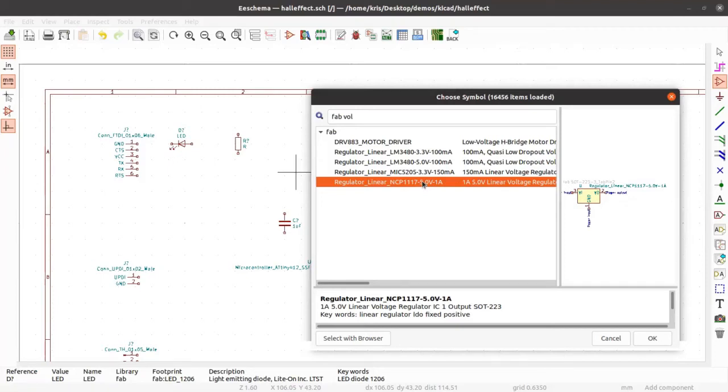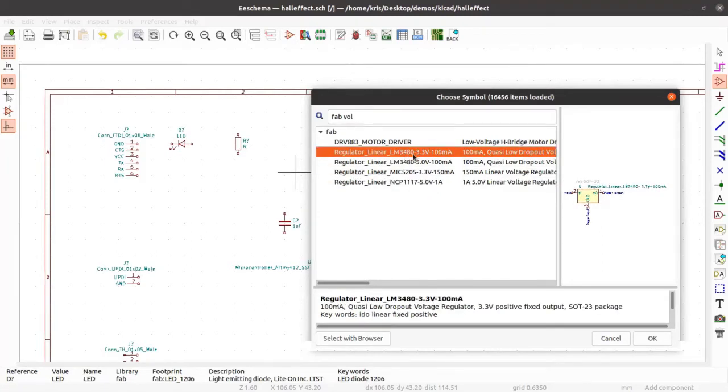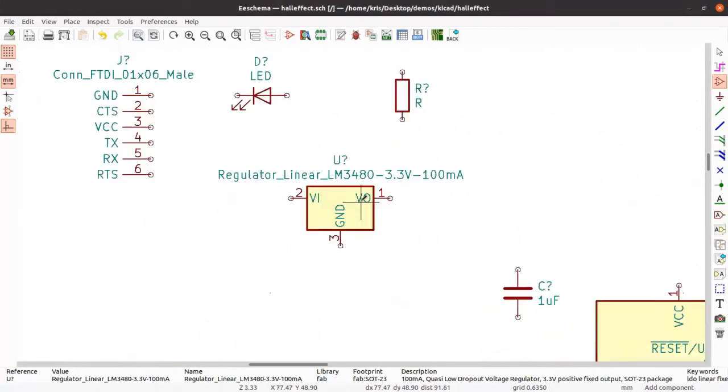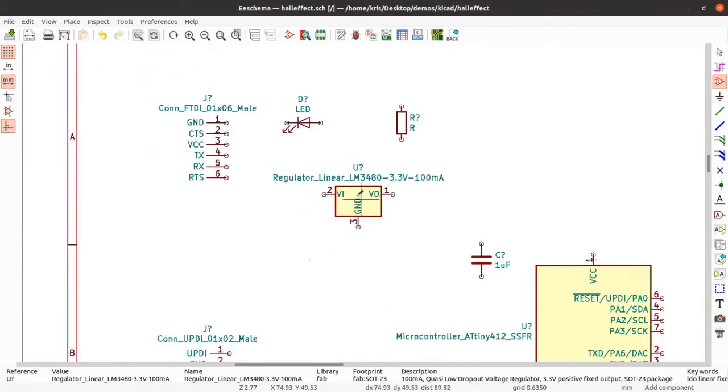Let's say you want to reuse the voltage that you are using for your motor driver, and you want to use that in order to power also the microcontroller. So if the incoming voltage is, let's say, 24 volts, then this chip is going to convert it to 5 volts. But in this case, we're going to take this one. It's just 100 milliamps, which is just enough for our purpose.